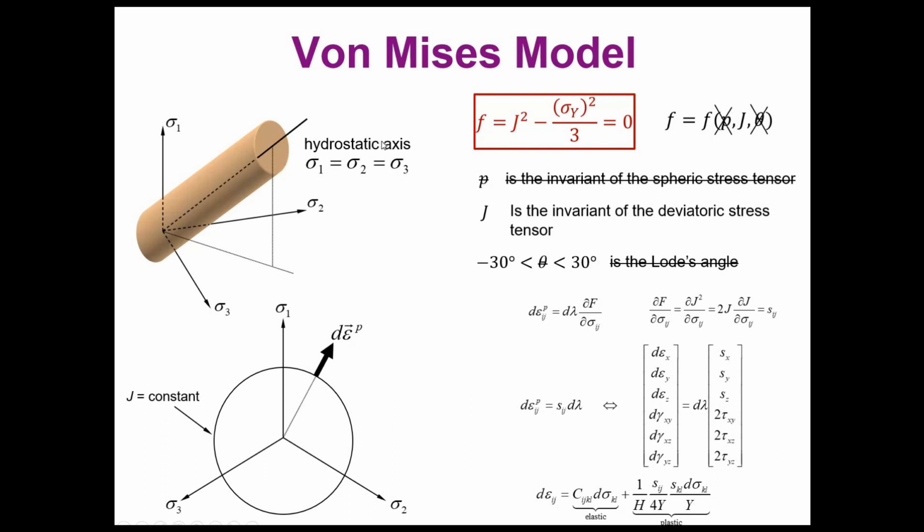Evidently, for these models that are thought for ductile materials, the failure is not going to be produced by hydrostatic loads that produce hydrostatic stresses. This makes sense because materials are very good taking these hydrostatic stresses, especially under compression and especially in the case of soils, for example, but not good taking distortions.